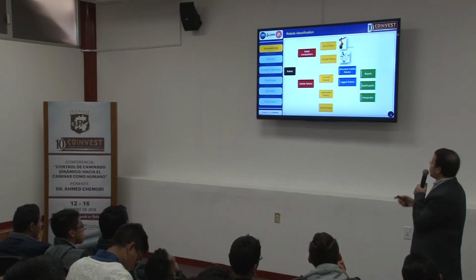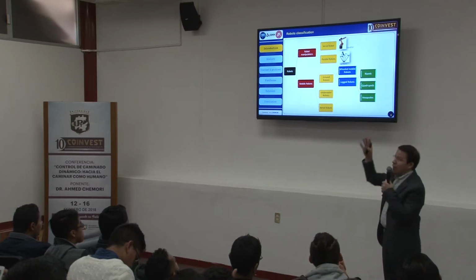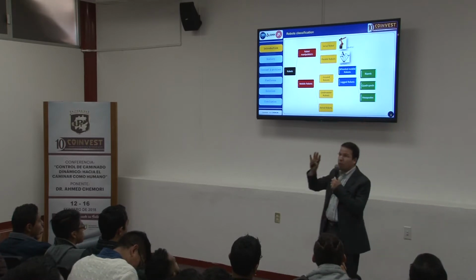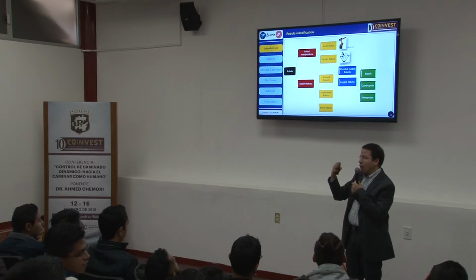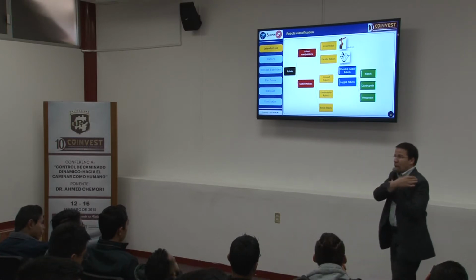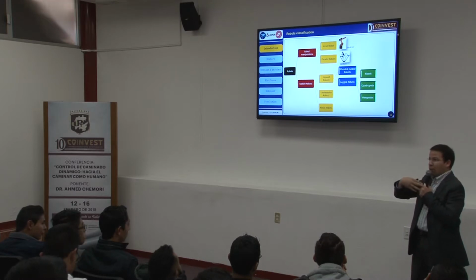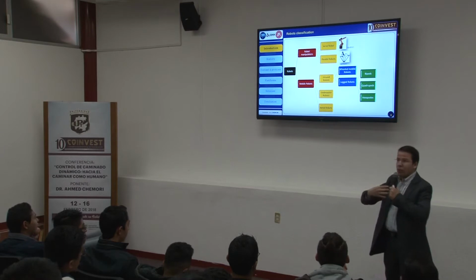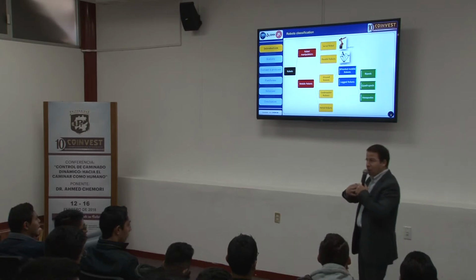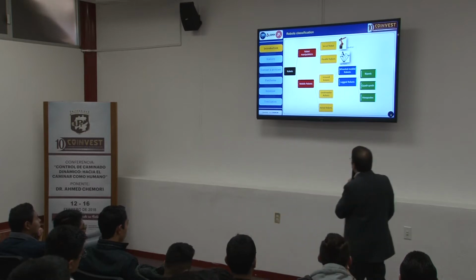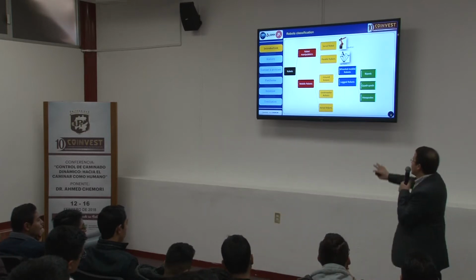The first lecture was on parallel manipulators, and I explained the difference between serial and parallel manipulators. Serial means that you have joint, body, joint, body, and so on in sequence, going from the base to the end effector. In parallel, you put at least 2 arms in parallel to have a parallel manipulator arm, or parallel kinematic chain.